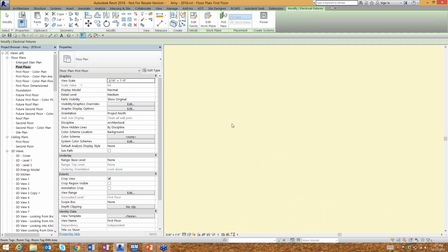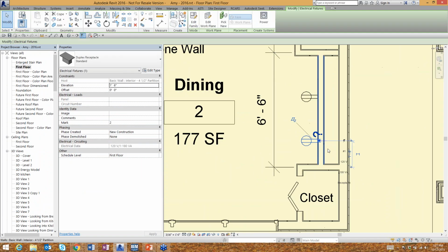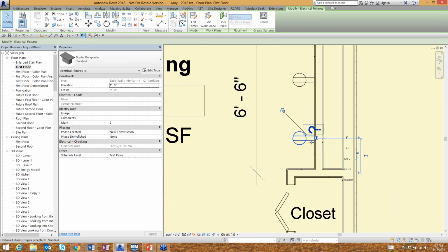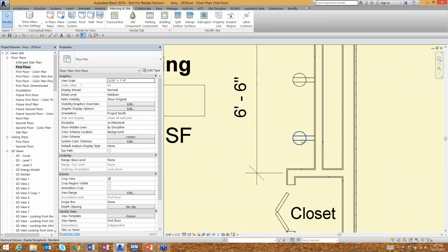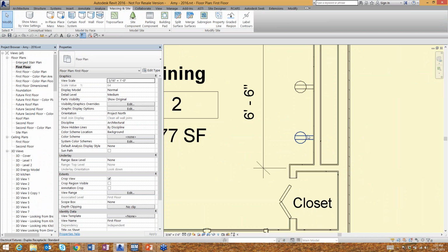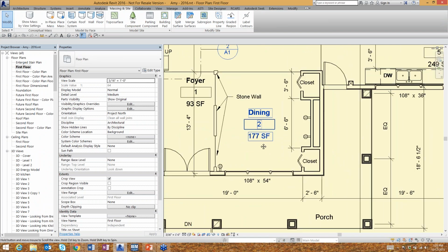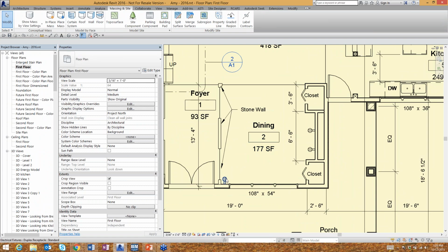So if you don't need the 3D-ness of it, we could just make a family that has nothing but the 2D lines here, just to show the outlet lines, just the symbology of it. So we can create 2D families or 3D families. They don't have to be 3D families. I guess we could insert an AutoCAD block and copy it around, but I would not recommend that.